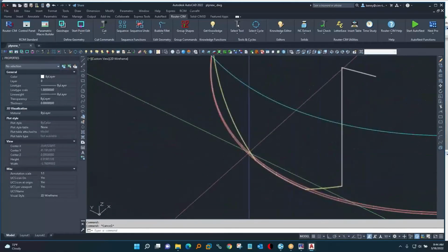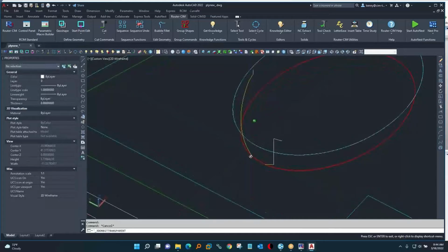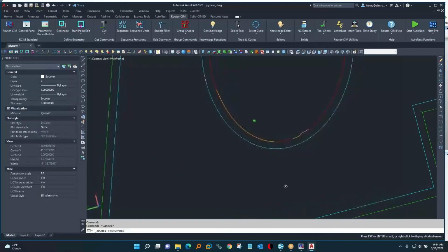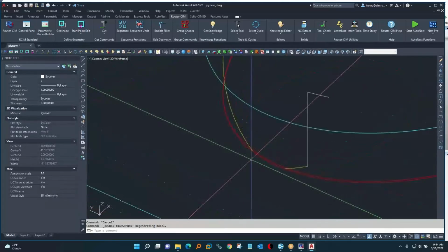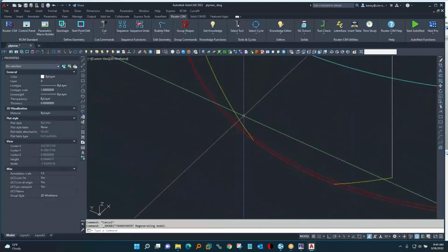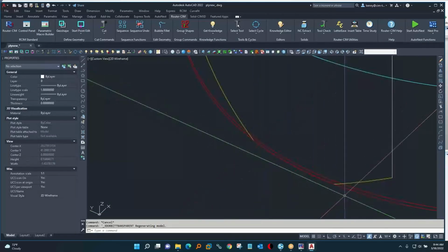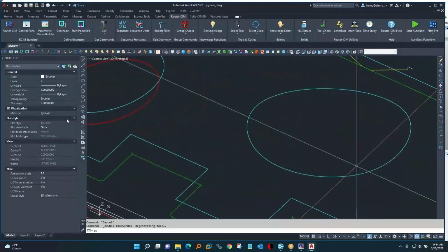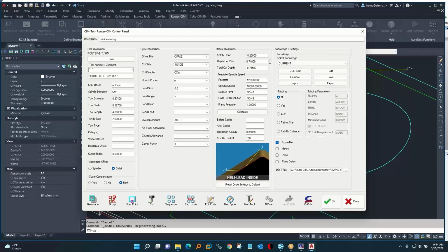So this is 2 passes. It ramps down right along the contour of the shape. Router Sim's the only one making a helical move like that, follows the contour of the shape, gets to the first level, cuts around the part, slides down to the second level, overlaps, leads out, cancels cutter comp. So instead of twice around the part, we can do something where we go, for example, 1.5 times around the part. We do what's called a tab at cut start, and I could put in a decimal percentage there.